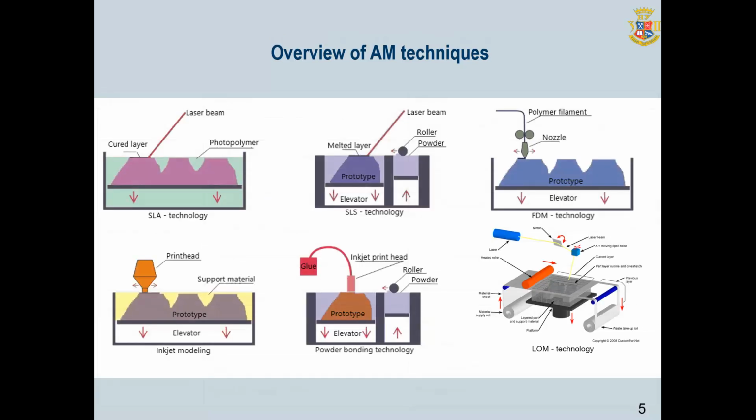Process equipment applies successive layers of liquid, powder, paper, or sheet material, building a three-dimensional model from a series of cross-sections. Some additive manufacturing techniques provide the use of multiple materials, as well as different colors within a single production run. For example, it is possible to print a model from one material with supports printed from another, easily soluble material, which makes it easy to remove support structures after the printing process is completed.